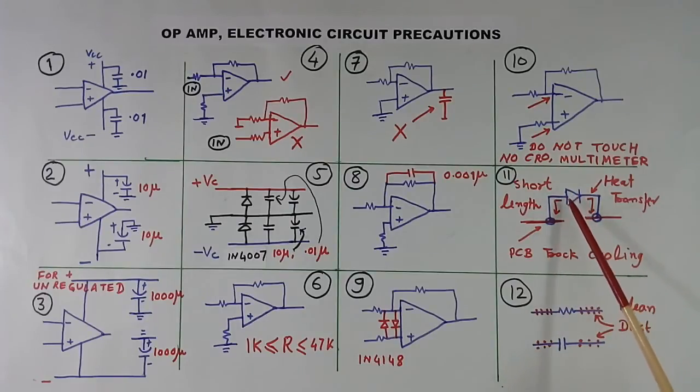They also specify what maximum length it should be. Keep this lead length short, otherwise this component will fail. A short length will help in better cooling.